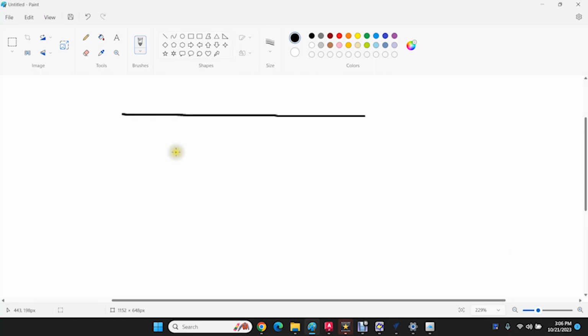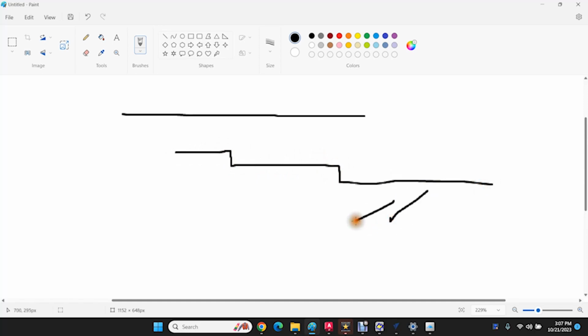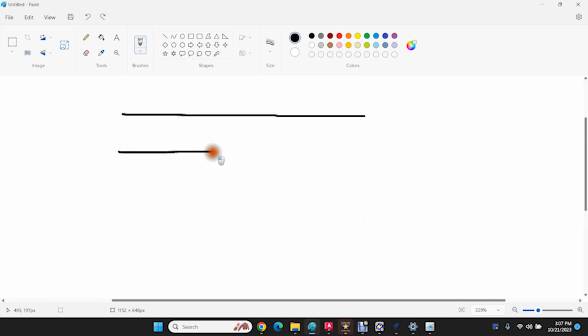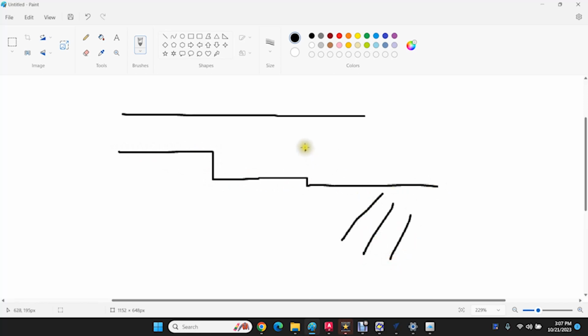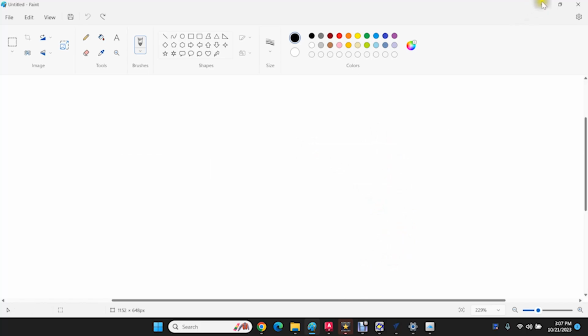If you're telling it to start at 1/8, it'll start at 1/8. And if you're telling it to cut 1/8, then this is going to be your finished depth. If you're telling it to start at 1/4 and then cut 1/8, you're going to have, pardon, 3/8 from here down to here, and so on.